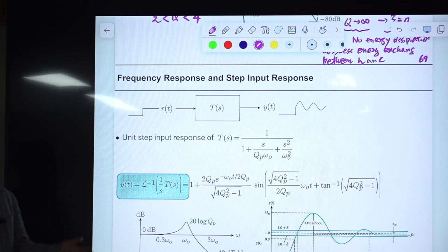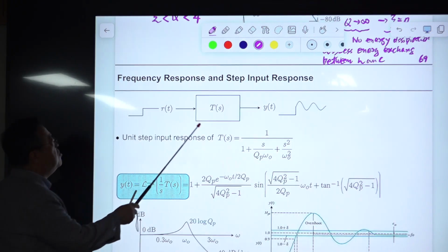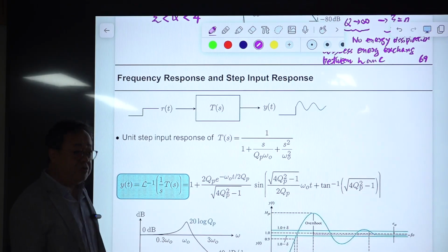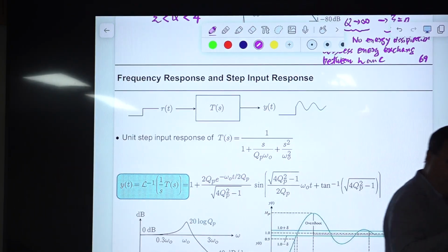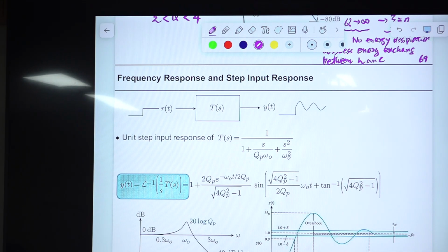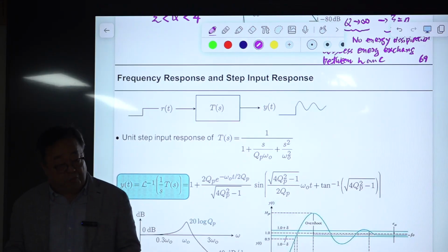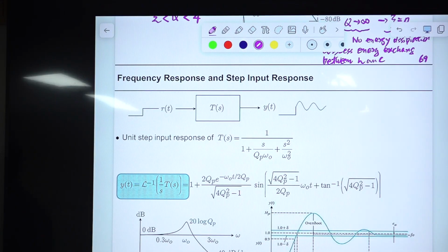If it provides good step input response, it provides good dynamic performance for any type of input. This is the one people use to evaluate performance in general. Good step input response means good transient response for any type of input disturbance, and that is why it is important. For the PWM converter, you are not changing the input voltage often. You are changing the load current very often. For this case, step load response is very important, so later on we will be discussing this in detail.